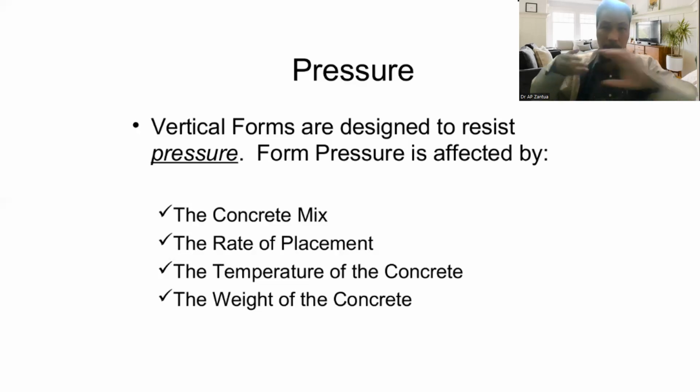Shotcrete is being shot out of the equipment, so there is a what? Additional impact force, okay, or fluid pressure, okay, that is being introduced. So rate of placement really has an additional effect.